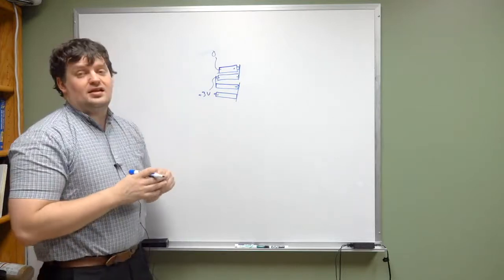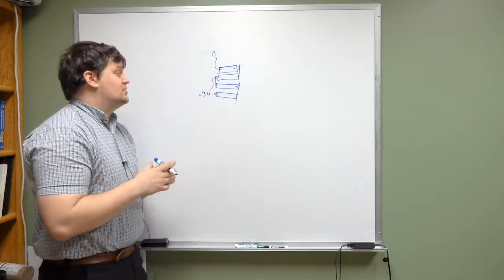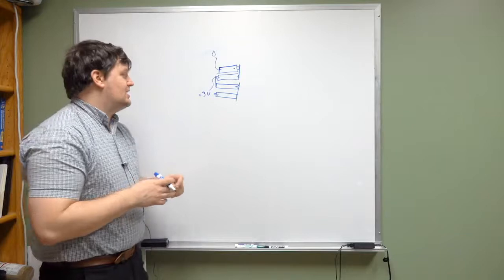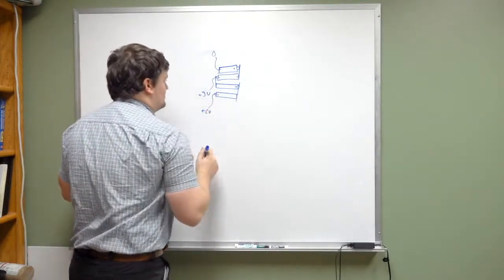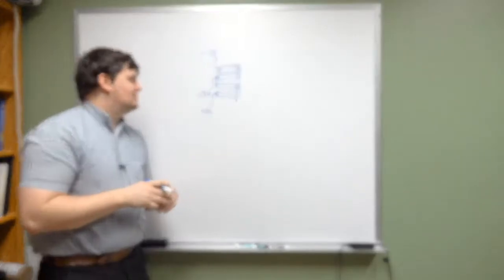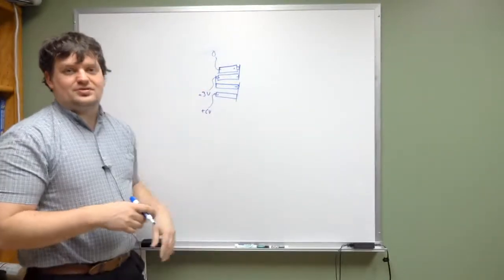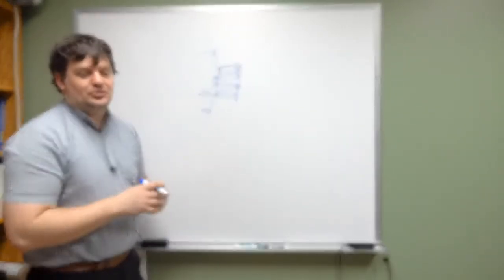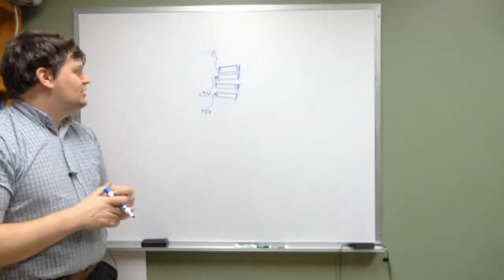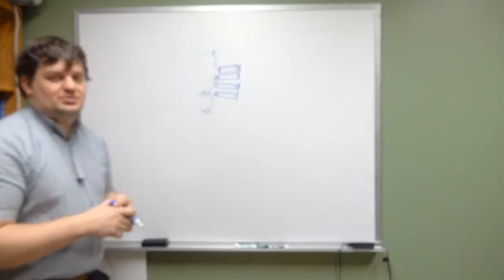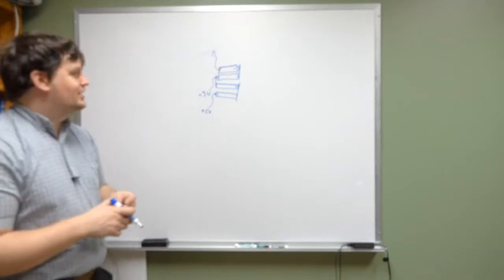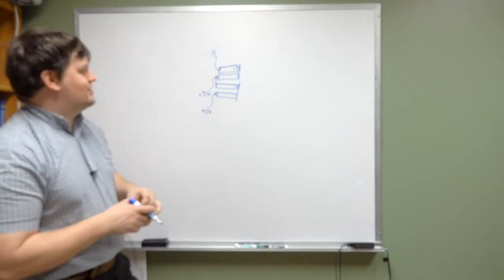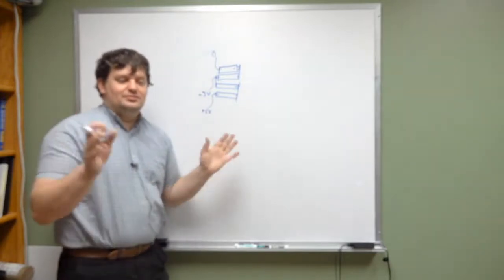Now you can get 6 volts out of this. You can't get 5. So here, this one's at 6 volts. And also, if you connect to that plate, you can get 3 volts out of it too. If you want to have variable voltage inputs, or some of your components take different voltage inputs, you can pull off of different sections of a battery. That would cause these batteries to drain faster, but whatever.